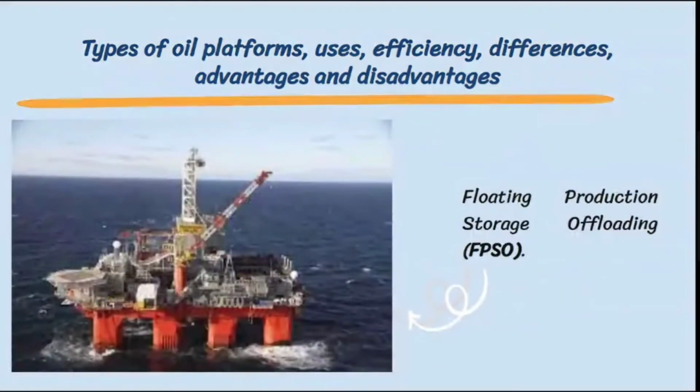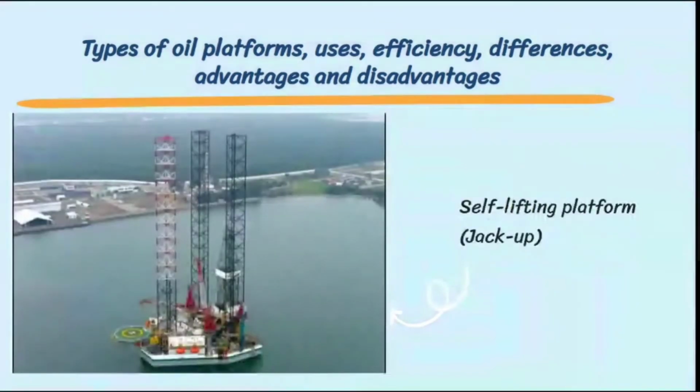The floating production storage and offloading unit, FPSO, I mentioned before. And then we have the self-elevating platform, jackups. This is the first production unit par excellence. It is a three-dimensional lattice supported on four legs with cylindrical tubulars to prevent buckling.